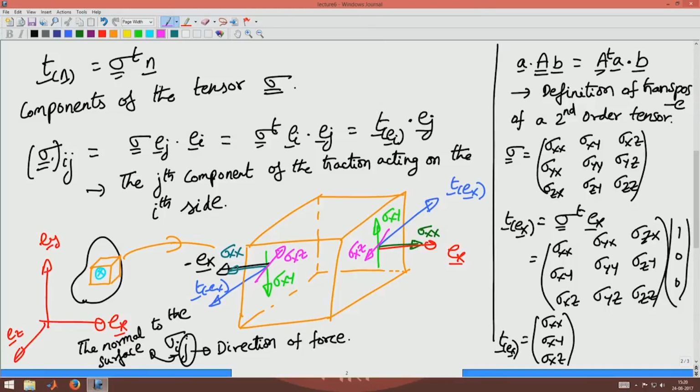Okay. So, in two faces we got the orientation of the stresses to be opposite to each other, but same in magnitude. In other words, what this tells us is the tensile stresses are positive. Sigma x x on the two faces are in opposite directions, they kind of pull the cube, and hence it is positive. This does not mean that we assume tension as positive, it is a consequence of assuming a coordinate system and writing the components of the tensor with respect to that coordinate system.